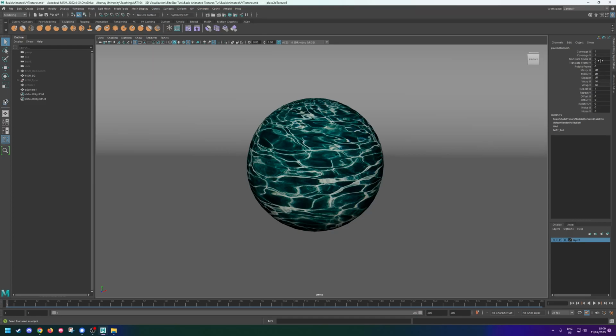Now, in the meantime, I'm just going to worry about translate frame on the U. So down here, I'm going to my timeline, and I'm not going to press anything. I'm going to right click on Translate Frame U and go Key Selected. And I can see now in my timeline, let's make this a bit bigger so you can see, it's not going to let me, typical. But I can see there's a keyframe there, and of course I get a little signal that there's a keyframe there.